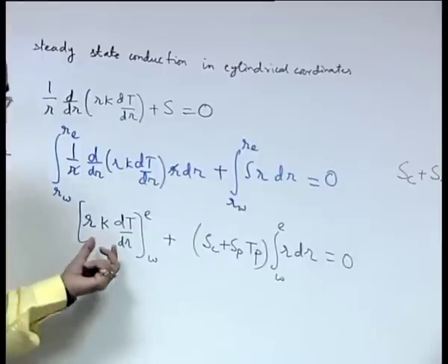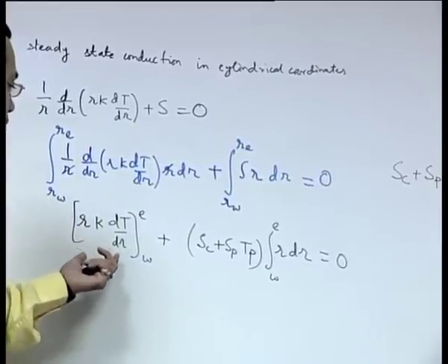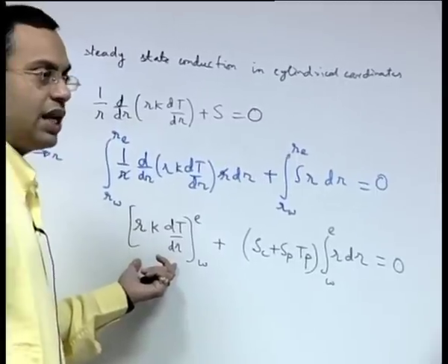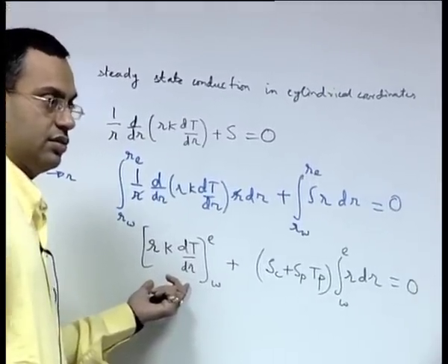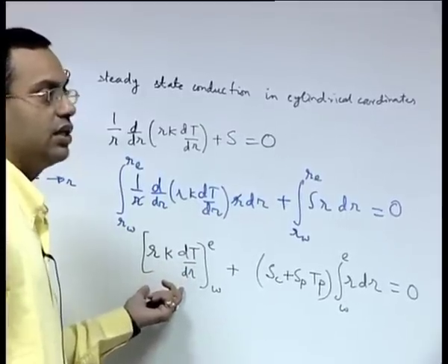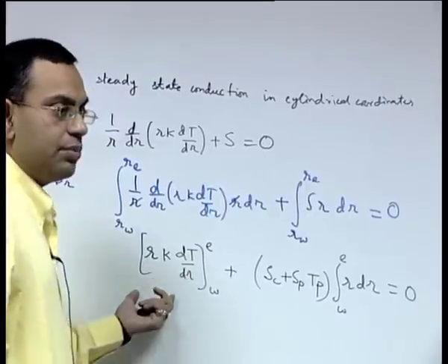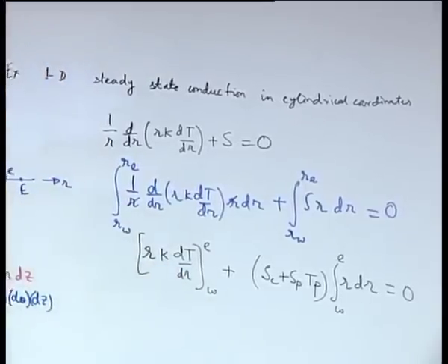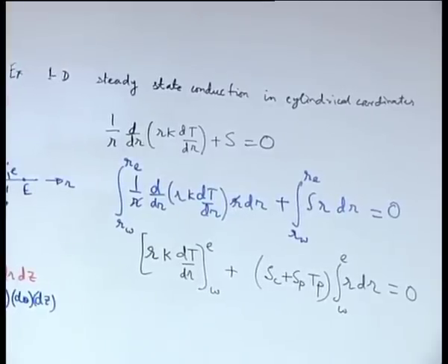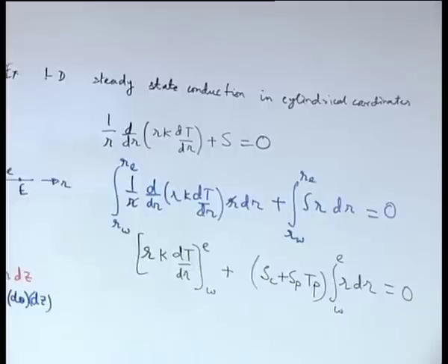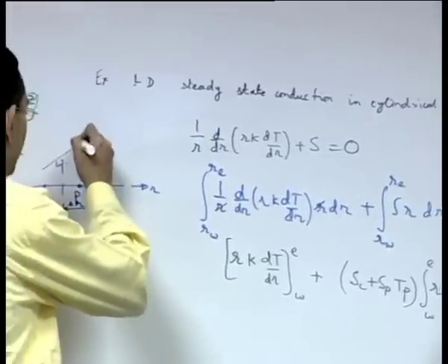In the next step, we have to make a profile assumption for dT/dr, or a profile assumption for T to evaluate dT/dr. So, what can be an acceptable profile assumption for T? Piecewise linear between the grid points. So, let us make that choice.